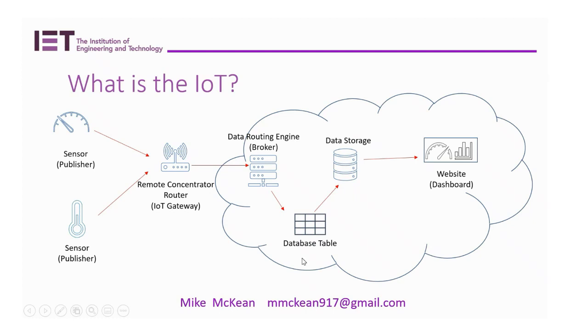And what is LoRaWAN? LoRaWAN is where you have a radio transceiver here, and these are LoRaWAN type sensors rather than M-Bus. And what happens is LoRaWAN is an environment that is switched on 24 hours a day and is free to use. But hold on, I'm going to tell you something different in a minute. And what LoRaWAN does is it says, send me your data. And it's typically very much like a smart homes environment, very, very small packets of data.